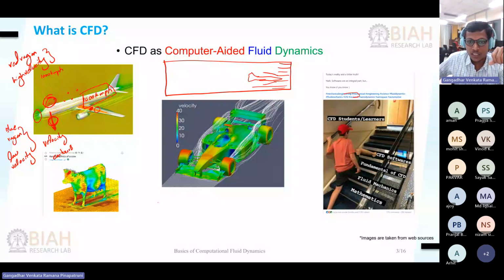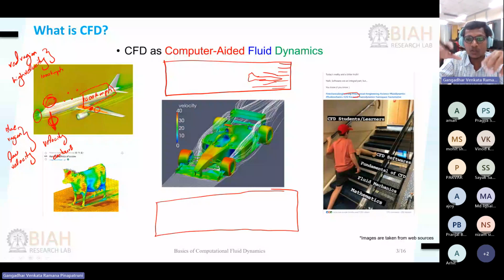If you do the same thing in a reverse way, then filling this entire domain means the amount of area that you are capturing in your simulation. That means you are not able to capture the whole sky or the whole earth in your simulation, right? For real life fluid, you can only capture a small amount of air or space in your simulation. So I'm capturing a small amount of space and now I allow my aircraft to travel. Suppose it is at position A, this is my aircraft and it is traveling forward like this. What is the amount of space it can travel? If this is my captured area for the simulation, suppose this is a 1 kilometer space. Okay.